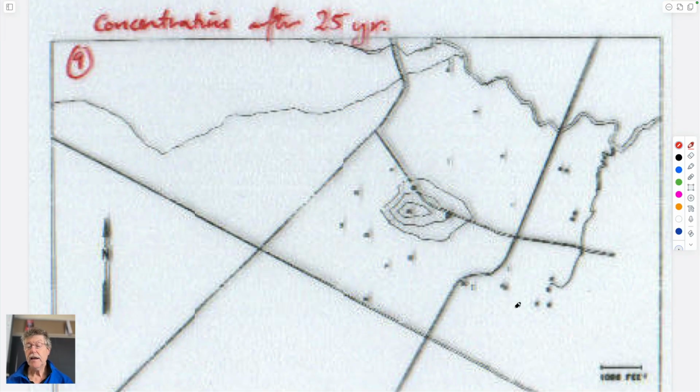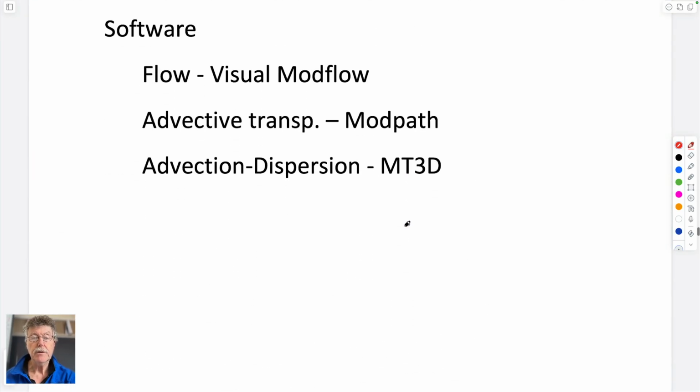What you want to do is how many wells, how much flow rate with a given aquifer configuration and permeability, and how long would it take to be able to remediate this plume as a result of that. And so that's kind of where we're going with this.